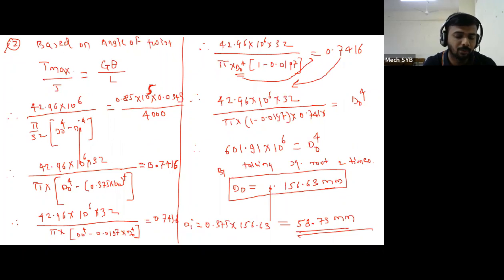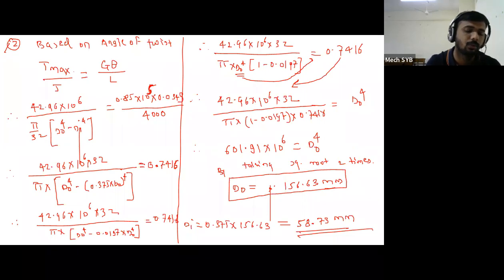So here you got the two values, therefore we made the comparison. But in the previous three problems we have solved, they have given only shear stress, and that is your final answer. Whatever diameters we calculated by using the shear stress concept, that is your final answer, because there is no comparison. But here we have to make the comparison, and after comparing, you have to check which values are maximum, and those maximum values we have to consider for the designing of the shaft. So after this statement, again write these maximum two values in your notebook.